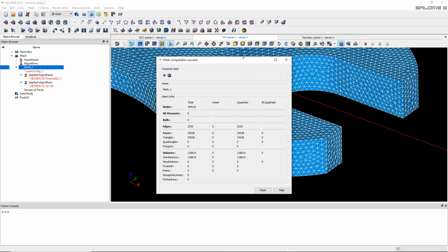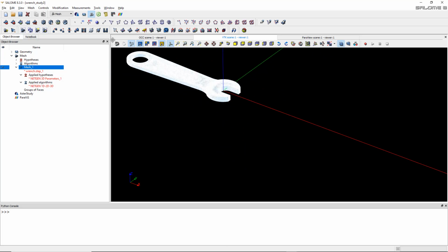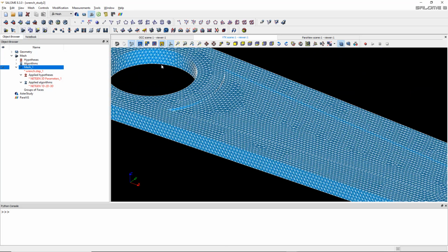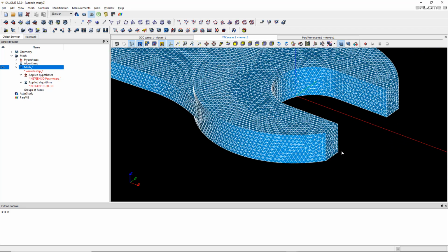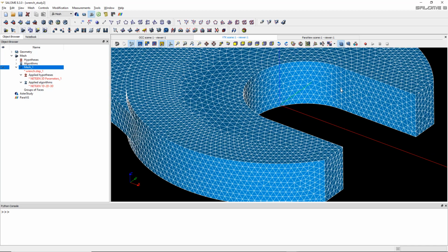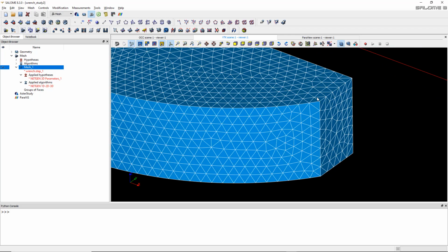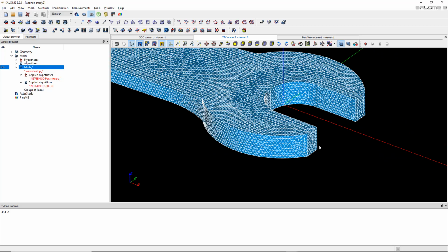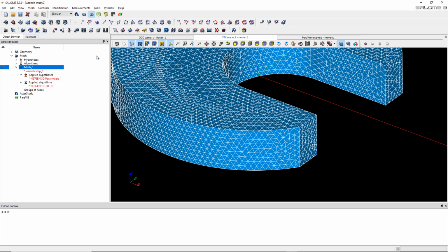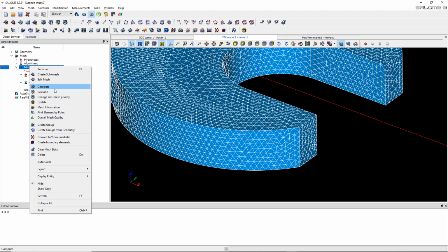So I just saw I have around 200,000 elements, which might be a bit much. So I'm just guessing because I had some tries and, actually, Code Aster and Salome Meca have some kind of limitation in terms of model size. You cannot calculate a million-element model, it would just crash your computer. So maybe it's a bit too much, especially since it's second order. Let's just decrease a bit the number of elements.